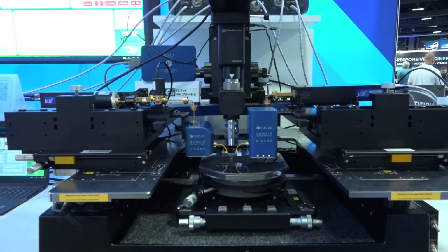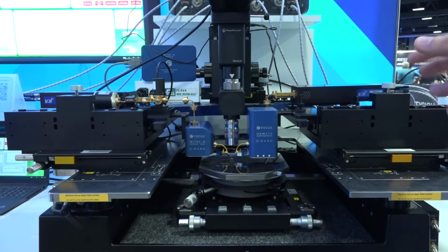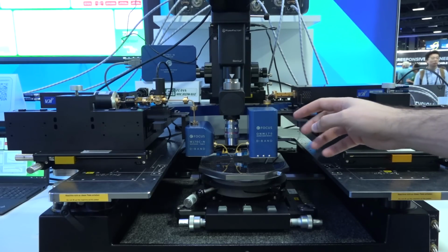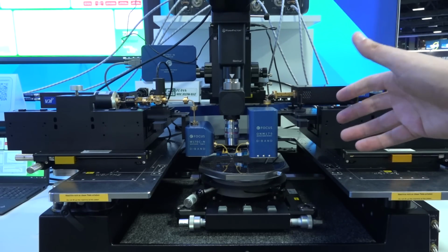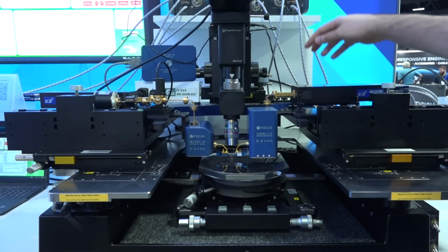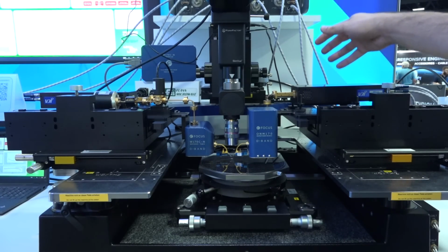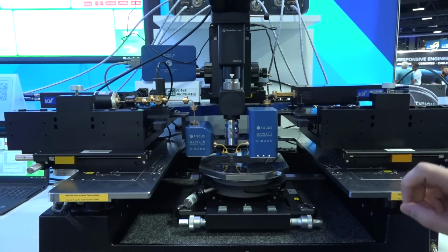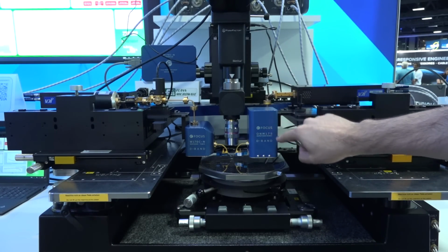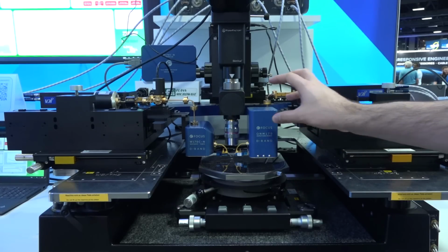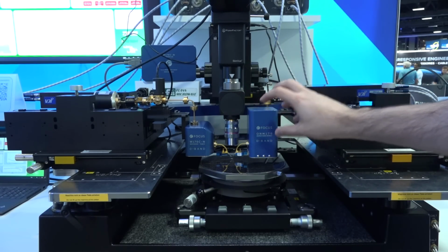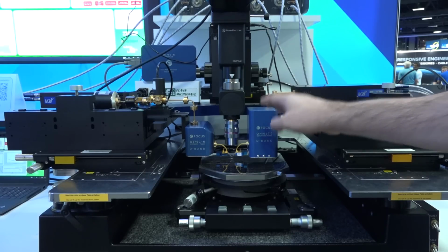Now measuring noise at D-band is a whole other problem, primarily because there are so many uncertainties that come up on top of each other at these higher frequencies, because every loss in the system is going to make things more difficult. For example, frequency down converters, as good as they are, still have considerable conversion loss and noise figure inherently. So in this setup where they're measuring D-band noise, they do have a front-end module specifically for noise measurement, where internally we have a low noise amplifier and essentially signal conditioning to make sure that you get the best repeatability of the noise directly measured at this.